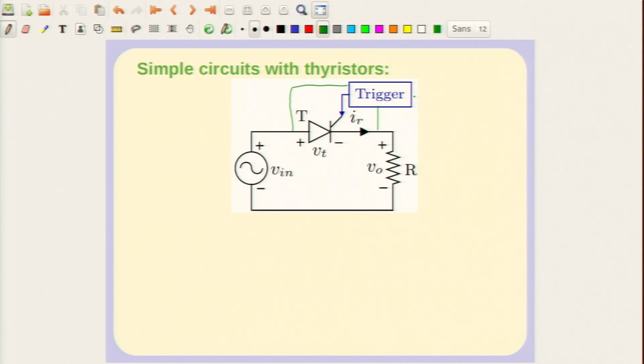So, the wish to fire it of course means that there is some control, and this in fact comes from some control circuit which tells you at what point you should fire the thyristor. So, this is what is known as an electrically triggered thyristor, where the power supply for the trigger circuit is also derived from the voltage across the thyristor. The trigger generates a current which flows through the gate, and this in fact flows into the trigger circuit as well. So, this is essentially a trigger, and the trigger is actually fed by some signal from outside.